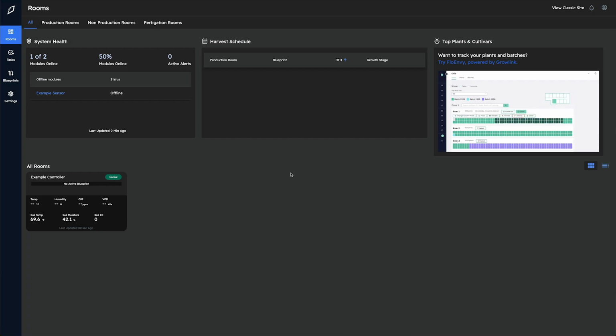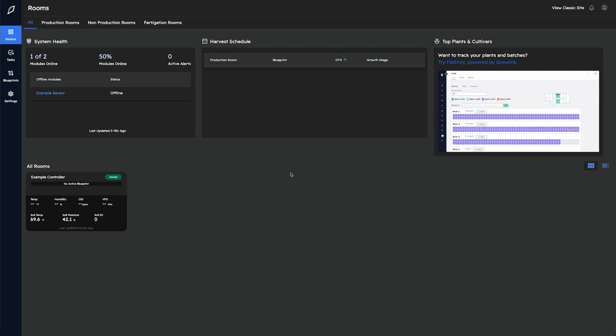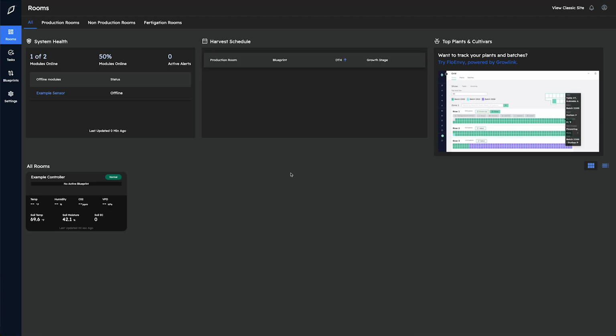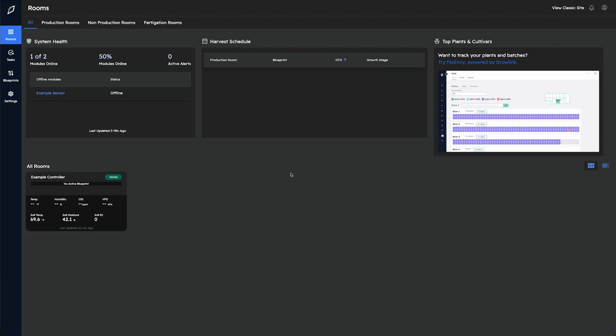In today's walkthrough we'll be going over how to make a sensor trigger that engages a cooling stage on an HVAC unit when it's set up as a dry contact. A dry contact is just sourcing voltage from the unit that gets passed back towards the unit when that relay is engaged. In those kind of setups, directly controlling an output on the controller turns the HVAC unit on and off. To make this sensor trigger to turn on that HVAC unit's cooling stage and off based on the temperature in the room, we'll need to make a sensor trigger on a specific controller.